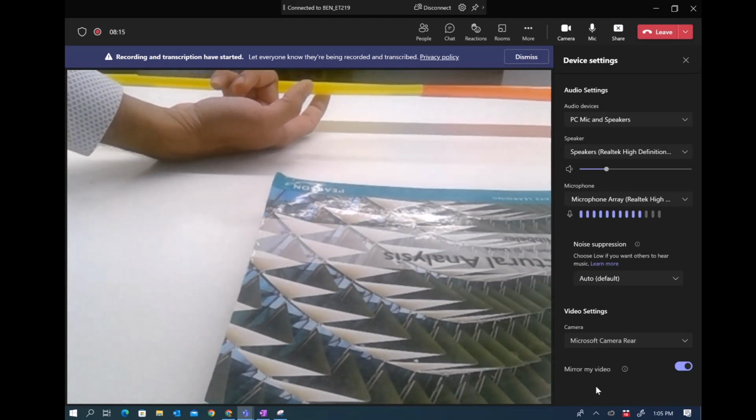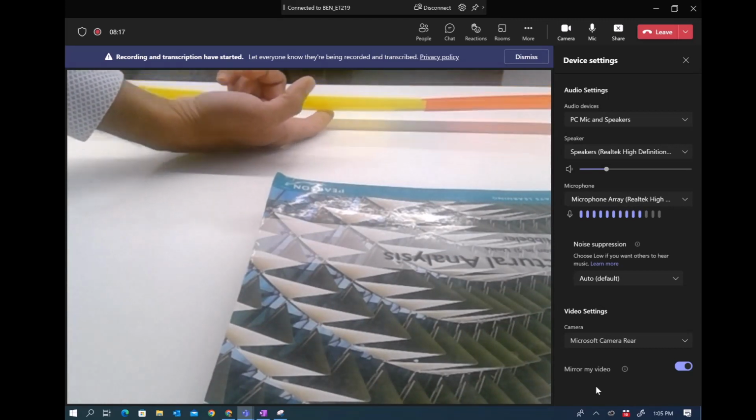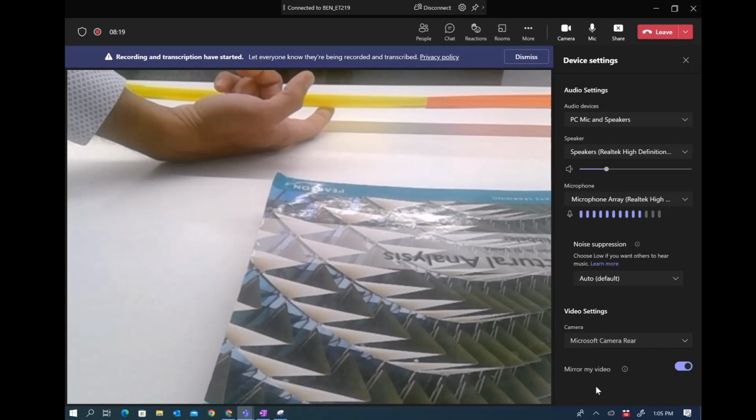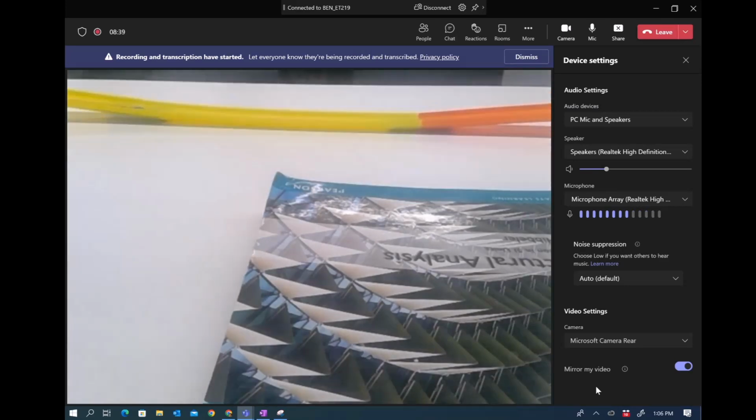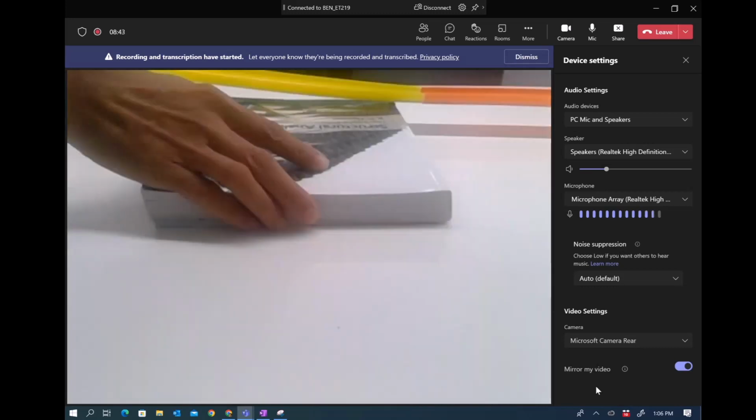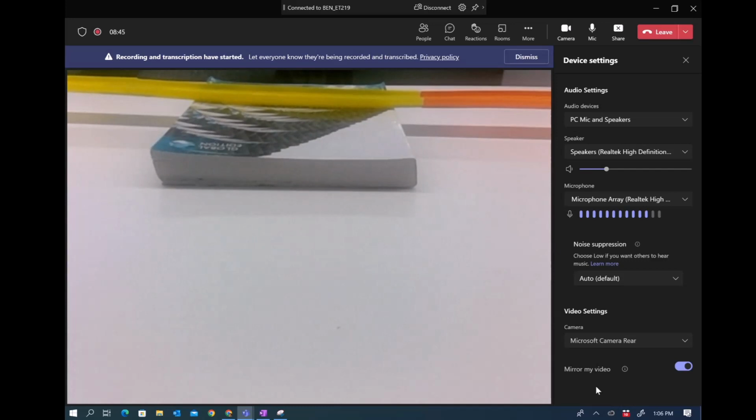Let's say that force is 1. We don't know how much force I need to push this back. Let's take it as 1, and let's say that the deflection is something related to 1. We can find it. We have methods to find the deflections when you have 1. Someone might say, no, but it's not 1, there was some value. So let's multiply that value by the real force and multiply the same with the displacement, and that will give you that unknown force. So that's the demonstration that I'm going to show you here.